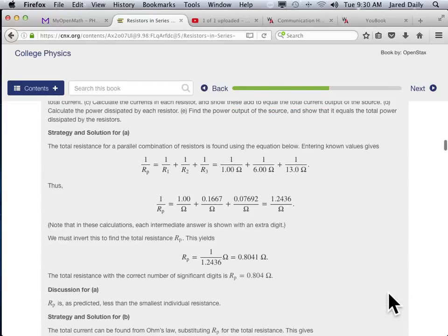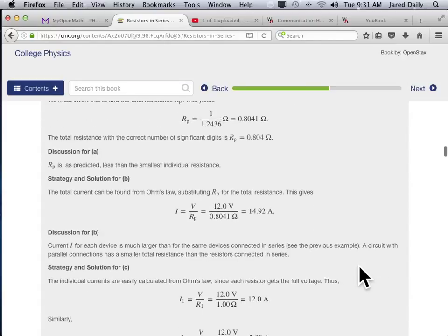So here's the question. You have two 500 ohm resistors and you want to make a 250 ohm resistor. How do you do it? Put them in parallel. Simple. If you have two 500 ohm resistors in parallel, you get 1 over 500 plus 1 over 500, right? That gives you 2 over 500. And then if you invert that, it gives you 500 over 2, which is 250. So two equivalent resistors in parallel give you half of one of those resistors for a total resistance, right? It's a quick way to create a resistance you didn't have before.